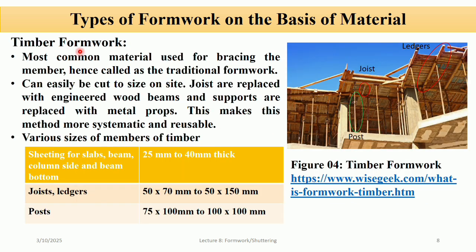Timber formwork. So timber formwork is a traditional and widely used type of formwork made from wood used to shape and hold concrete in place during the construction process. So the benefits or the purpose of providing timber formwork is that it is cost effective compared to other types of formwork such as steel, and it is a familiar material for many construction workers, making it easy to work with, and it can be used for complex designs, and it is environmentally friendly.